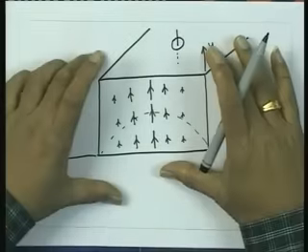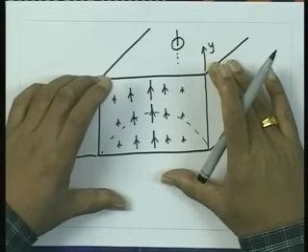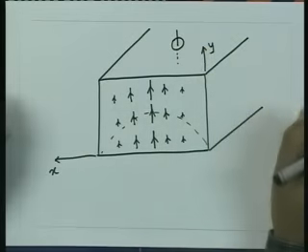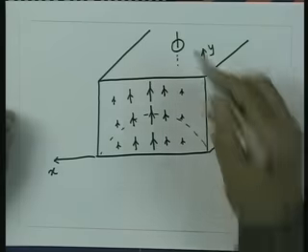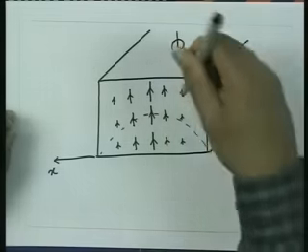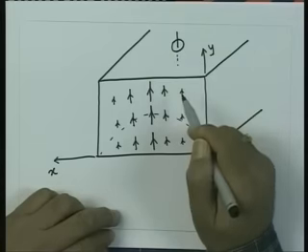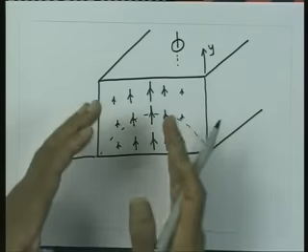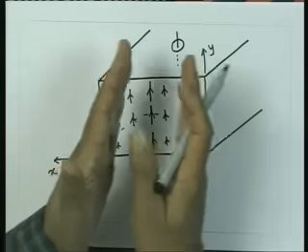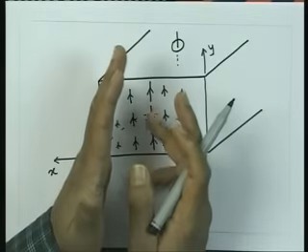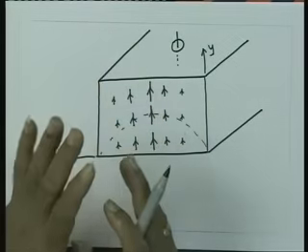Now the modes which we talked about are the field distributions which satisfy the boundary conditions. Here we are exciting the field, which is a sudden change of electric field at that point. Then one can show that to satisfy the boundary conditions for the field, you require all possible modes of the waveguide, whether they are travelling or decaying, because these are essentially the orthogonal functions which satisfy the boundary condition inside the structure.